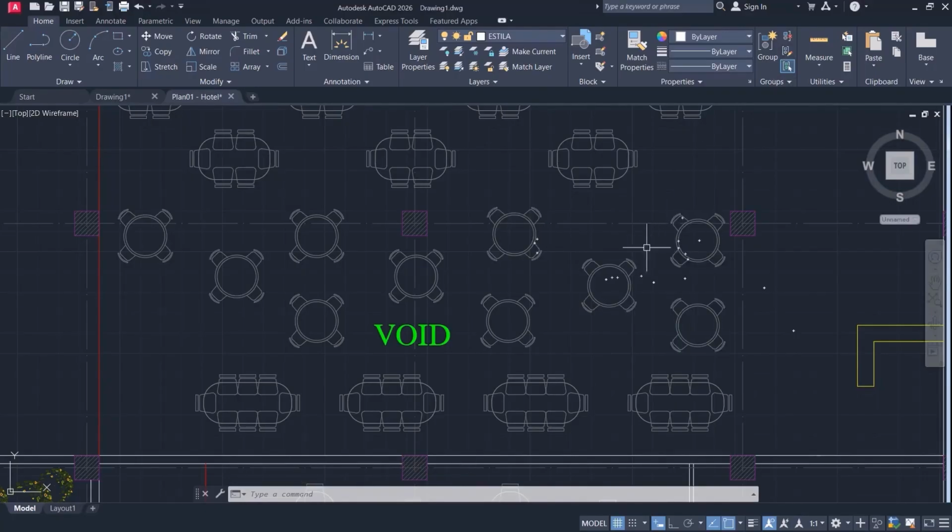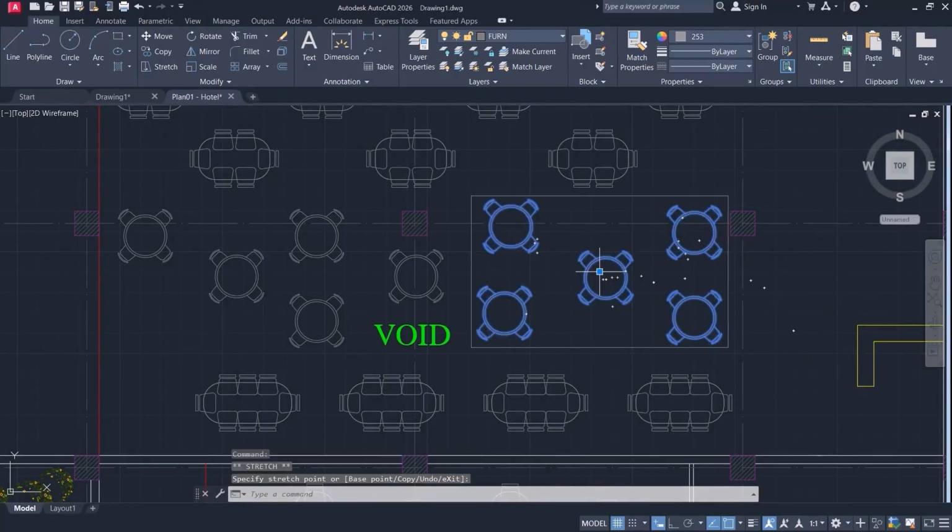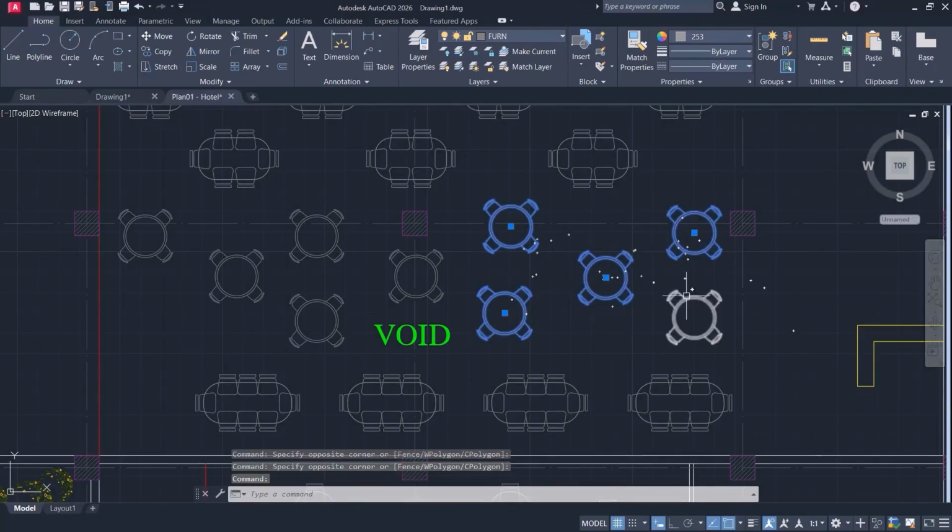In the scenario we looked at, in Edit Group, I select the whole group. I click on Edit Group. If I click on Add Object and select this, then press Enter to finish, the job is done. All of these are one group, meaning we don't have a nested group. The object we added was placed in the same initial group layer, and if I ungroup, there are 5 separate objects.